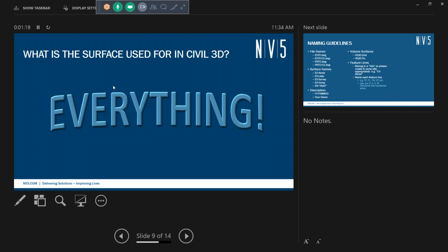There's a couple things that we need to do. A, discuss it with your project manager and also the surveyor. See how accurate their GPS was that day. How does it compare to other days that they were out on the site? Are you seeing some variation in your survey data? Analyze it a little bit. The other thing too is make sure to note on your plan to field verify all your join elevations. Cover yourself a little bit. Build some verbiage in there to kind of let you off the hook. Put it on the surveyor, put it on the contractor. So field verify on any join and match elevation.